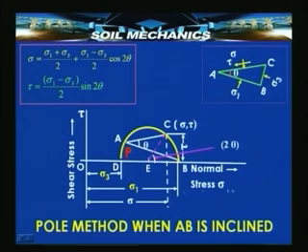The difference will be that from the point B now, rather than drawing a line horizontally to represent the plane on which stress is sigma 1, now we will draw a line BA which is parallel to the known direction of BA on which sigma 1 is acting, and where it ends, that is the point P. And from P, if you draw a line PC at an angle theta that is parallel to AC, then you get sigma, tau.